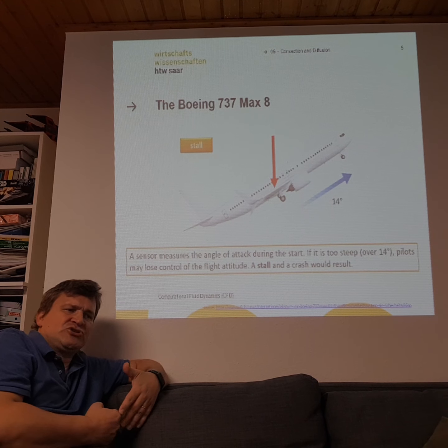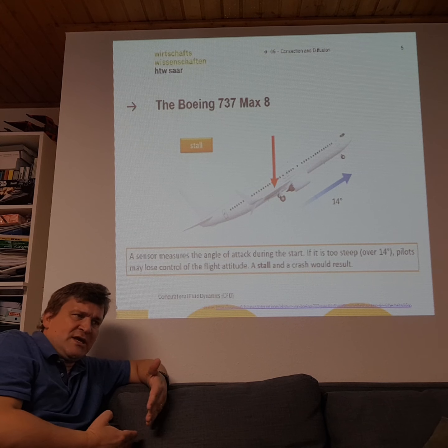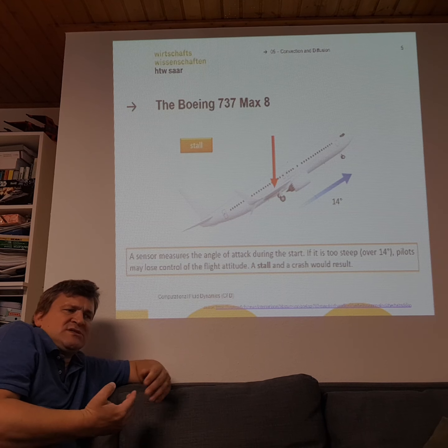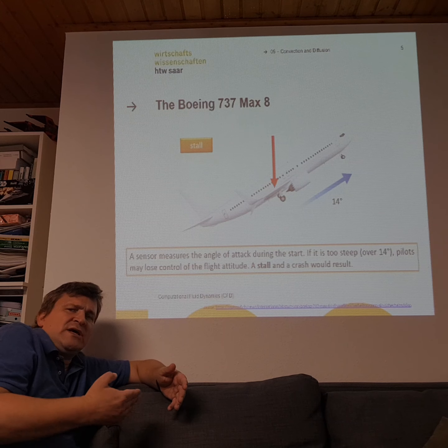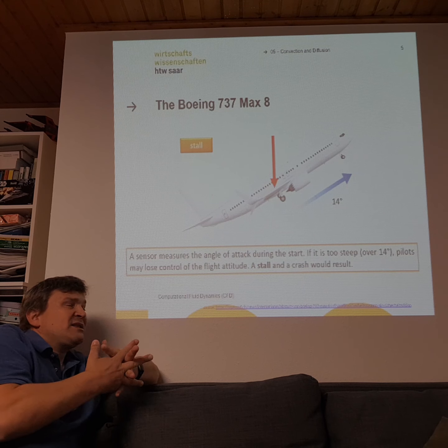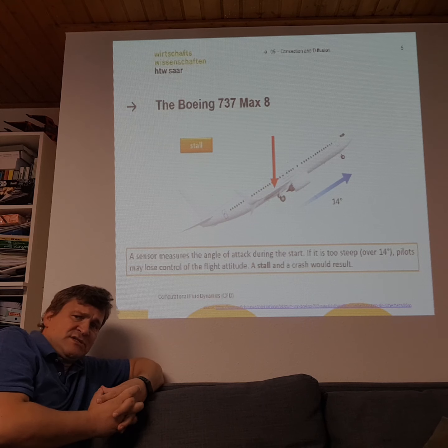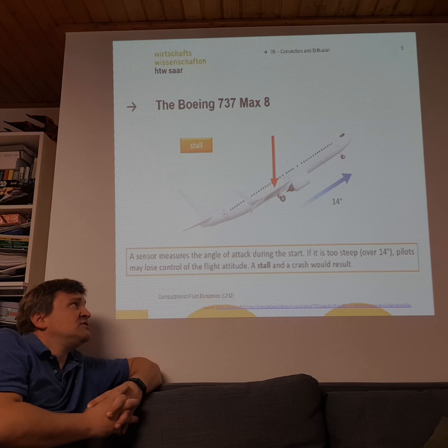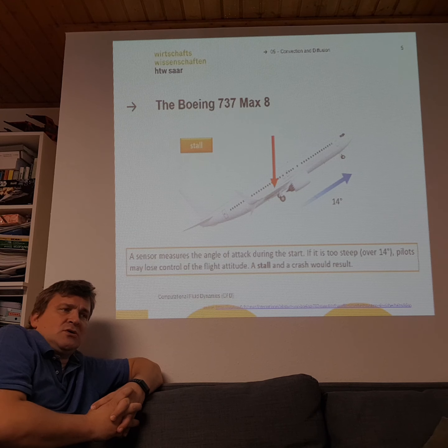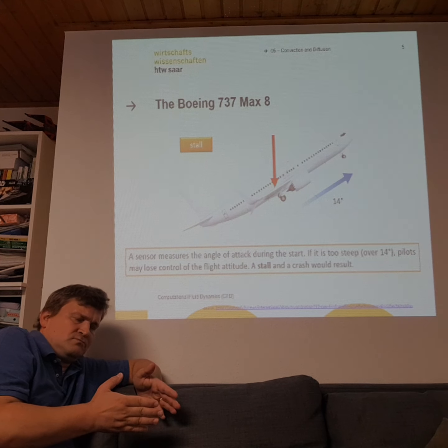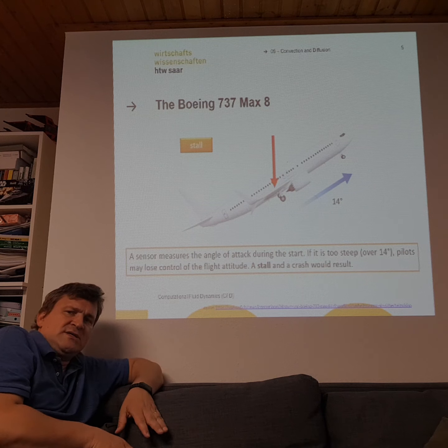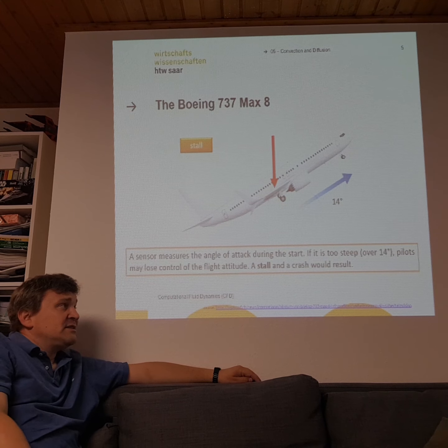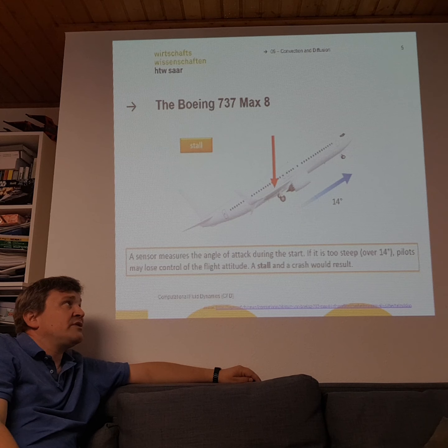This prediction of stall is really complicated, and normally a CFD code will calculate much higher forces. But in reality, we have the stall effect. In reality, we have this highly turbulent fluid flow, and this will cause a large decrease of the lift forces on the wing. And this is, of course, not good for the airplane.